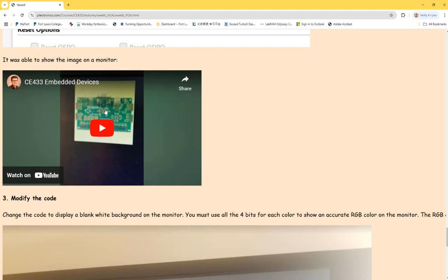That is because we do have 12 bits, but to make it simple, we're only using 8 bits to resolve it. So we're dropping 1 bit for 2 colors and 2 bits for another color. So totally we dropped 4 bits to reduce it from 12 to 8. You'll be able to see that later. Don't worry about that for now.